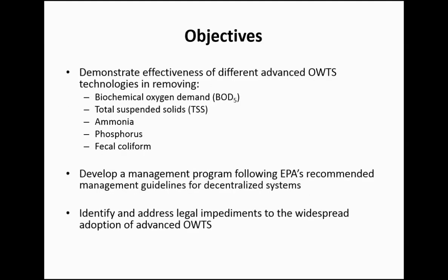The objectives of this project were to demonstrate the different types of advanced wastewater treatment system available, and also removing BOD, total suspended solids, ammonia, phosphorus, and fecal coliform. Another objective was to develop a management program following EPA's recommended management models in the voluntary national guidelines. Third objective was to identify and address legal impediments for the widespread adoption of this system by changing the regulatory bodies and wastewater industry perception of these systems in order to be accepted in the state.